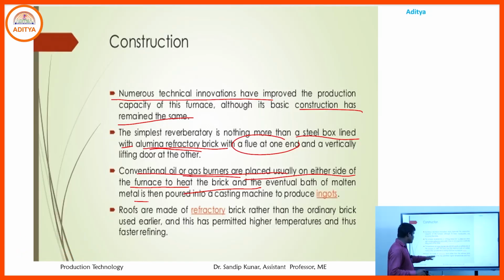The roofs are made of refractory brick, generally, rather than ordinary brick. Roof means the upper side of the furnace. Refractory brick withstands higher temperatures, because during melting a very high temperature is produced in the furnace, and ordinary brick does not withstand it, but refractory brick does.